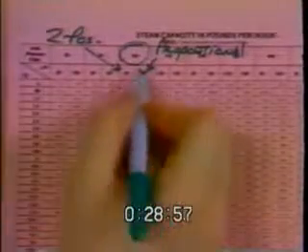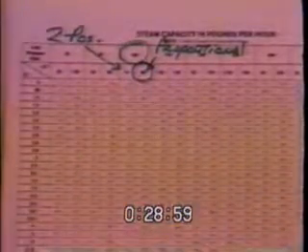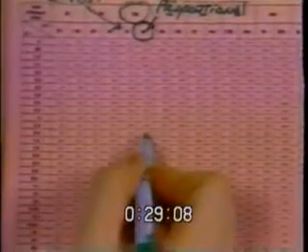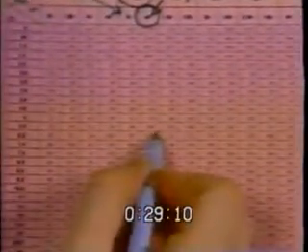In our example, we wanted proportional control for the steam valve. So we will go down the pressure drop of 8, going down this column until I hit my quantity of steam that I had. In our example, again, approximately 220. 215 is as close as I'm going to get. Taking this all the way to the left, the CV that I want is 6.2.